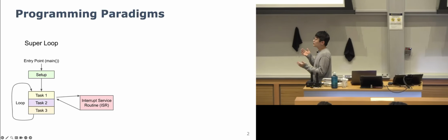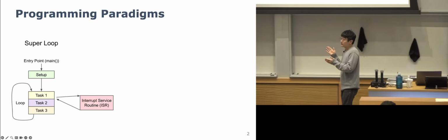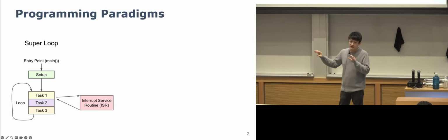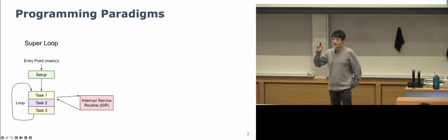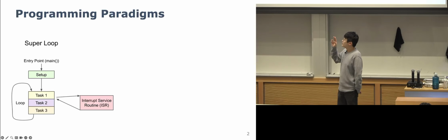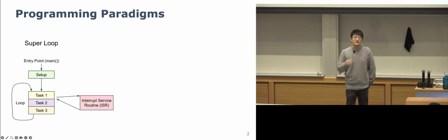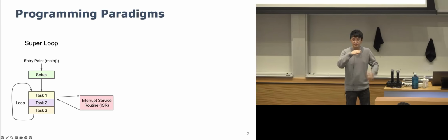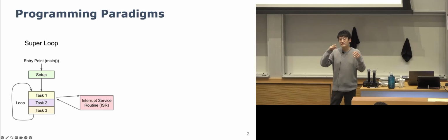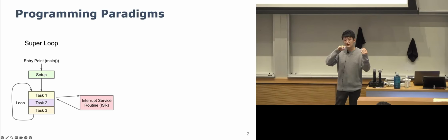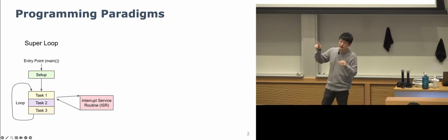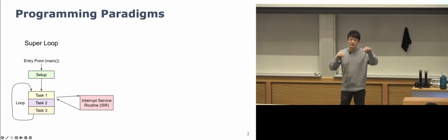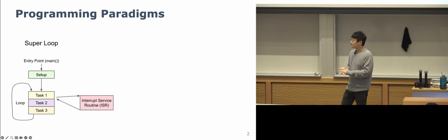Basically, each of the peripherals has its own ISR number, so whenever something needs to be triggered, it raises that interrupt request, and the request goes to the NVIC. Depending on the priority and the mode the code is running in, the NVIC decides when the core will execute the ISRs, the interrupt service routines, basically the functions that each of these interrupts corresponds to.